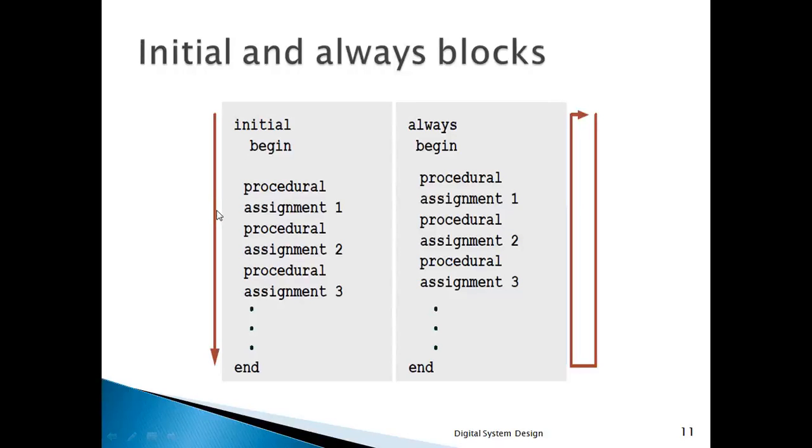This figure shows the hierarchy of statements. As you see, the initial block will be executed once and it ends, but the always block is repeated continuously as per the design.